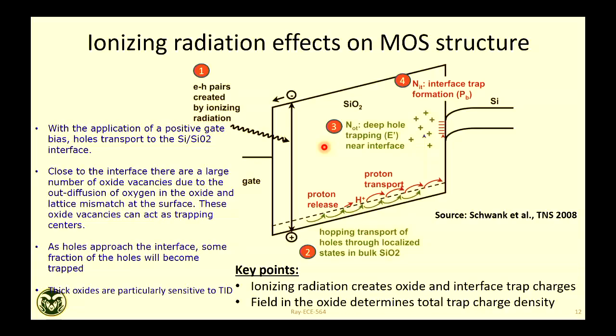But there are many cases where the oxide thickness is large. For example, flash. In flash, you cannot have a thin oxide, or there will not be data retention. In flash, you have to have fat oxides. That means flash will be much more sensitive to these TID effects. Questions?